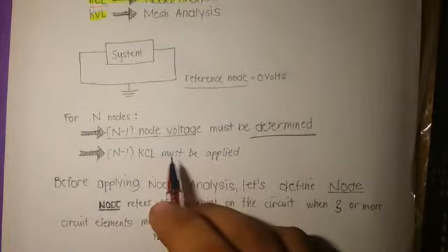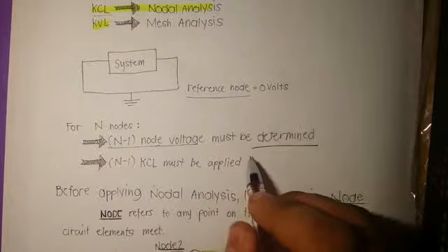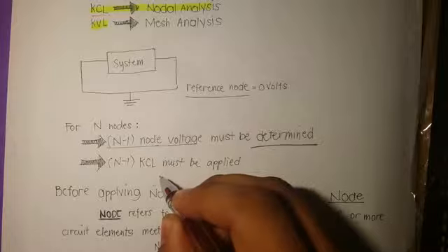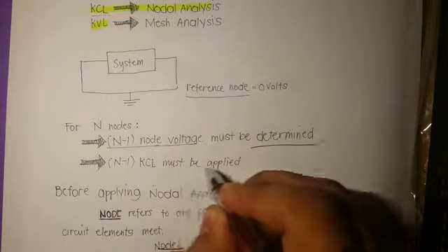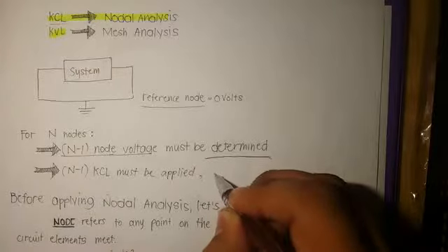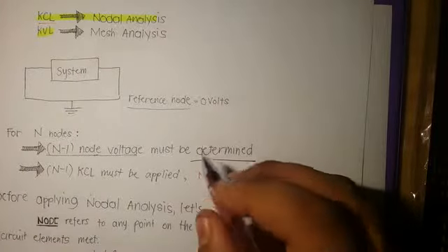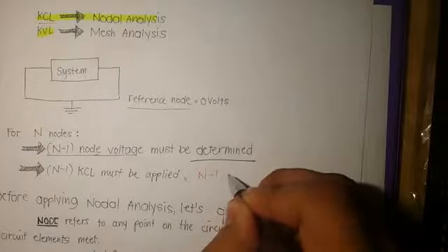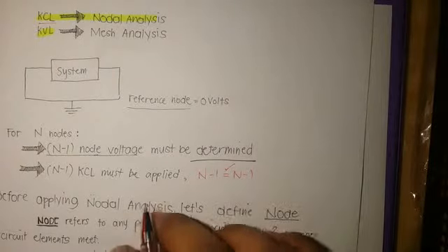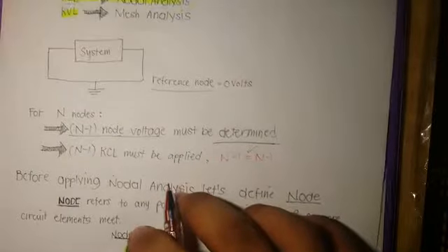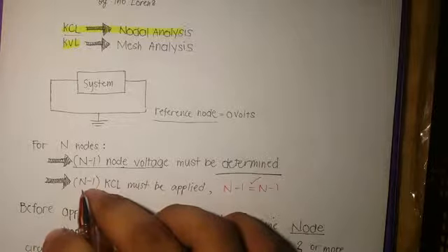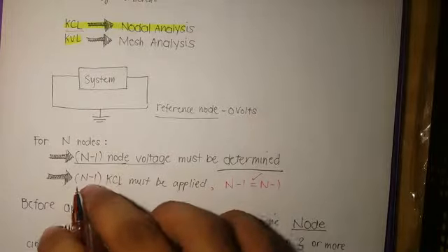All other voltage levels are then found with respect to this reference level. For a network of n nodes, by assigning 1 as a reference node, we have n-1 nodes for which the voltage must be determined. In other words, the number of nodes for which the voltage must be determined using nodal analysis is 1 less than the total number of nodes. The result is n-1 nodal voltages that need to be determined, requiring that n-1 independent equations be written to find the nodal voltages.